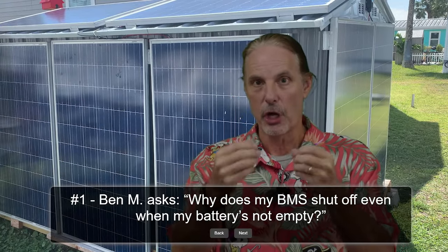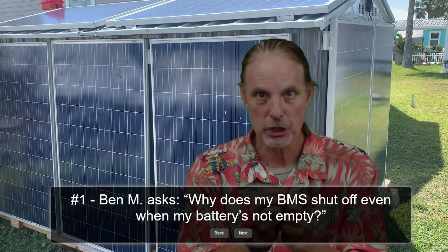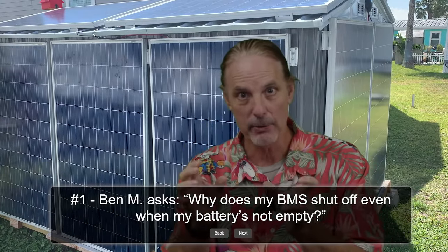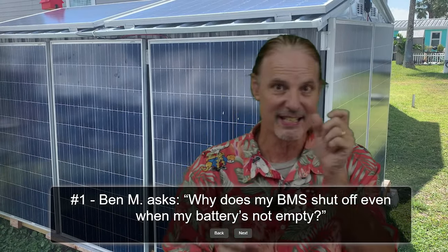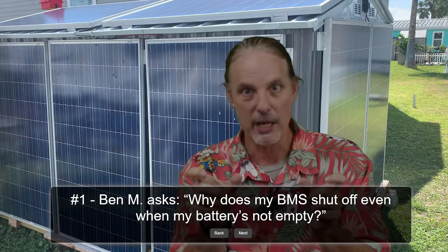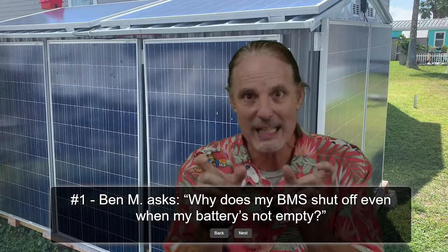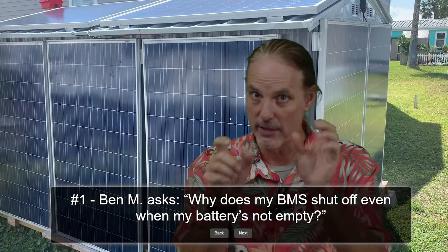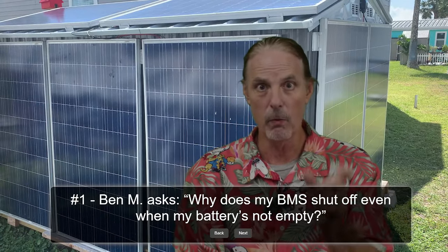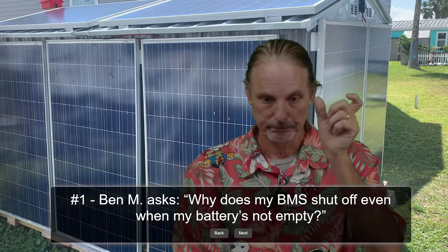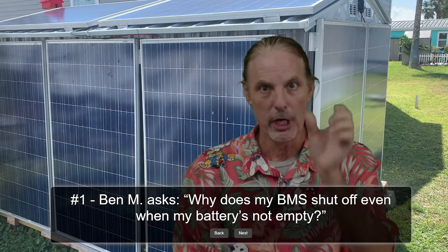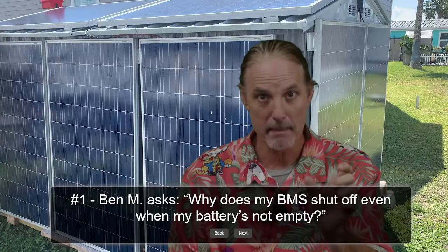And if your calibration of that battery BMS is not precise, or the equipment that you're using for that BMS isn't high enough quality, that state of charge will be wrong. So the two leading causes to it being wrong in this scenario is going to be, one, the actual calibration of that BMS is wrong.